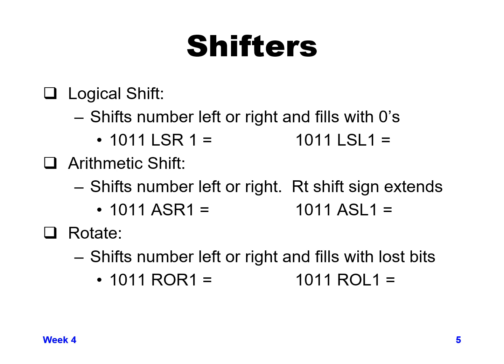The logical shift shifts a number either to the left or the right. So you need to say whether you're doing a logical shift right or a logical shift left. If we're shifting to the right, then every bit goes from its current value to one position to the right, so one position lower.